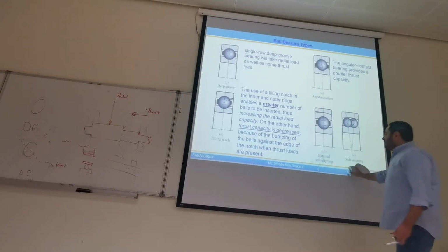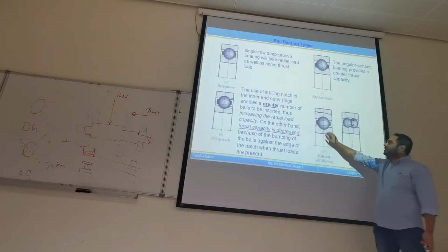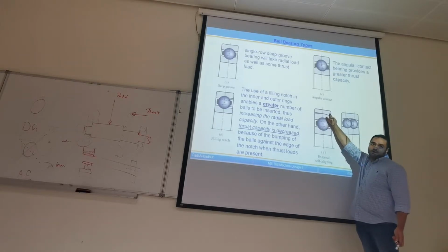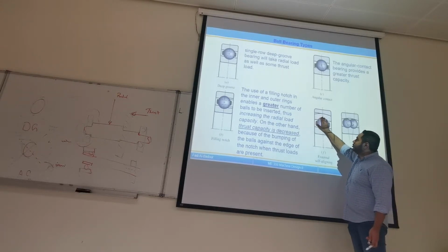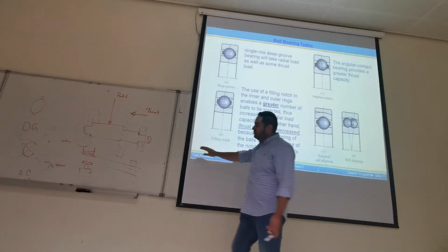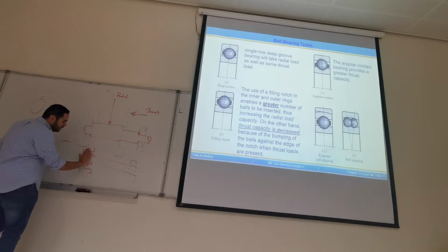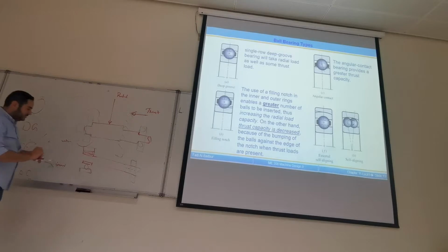We have two types of self-aligning bearing: the external self-aligning bearing, and the self-aligning bearing. In the external, there's an additional part that's going to be fixed to the housing. So if the housing is not aligned perfectly, the inner part of the outer ring will tilt. So the whole thing can tilt up and down. Okay? So if I have a misalignment like this one, no problem. Both the inner ring and the outer ring will tilt while there's a stationary part here. This is the line you see in the picture.